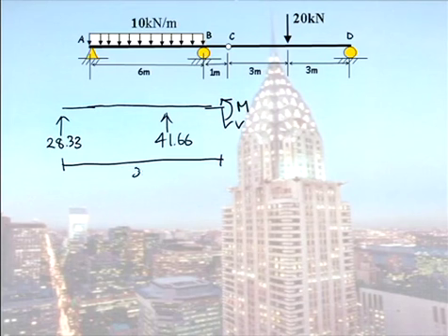So when I cut this beam, I'm cutting at a distance x, and that x represents anything from 0 to 7 metres. So I'm not cutting it at 7 metres, I'm not cutting it at 3 metres, I'm cutting it at x metres. And the equation I come up with using singularity functions will be appropriate for all values of x in there.